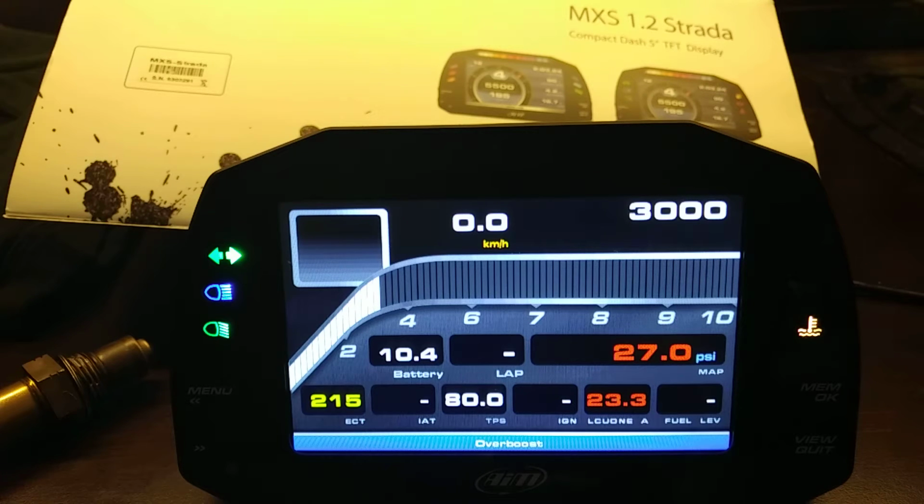What's nice, the fact that it's conditional, is that if we remove the engine RPM, some of these alarms will go away, and then the throttle position obviously will go away. This would be important for things like oil pressure. So if we have an oil pressure here of 40 psi, that's okay with the engine running.